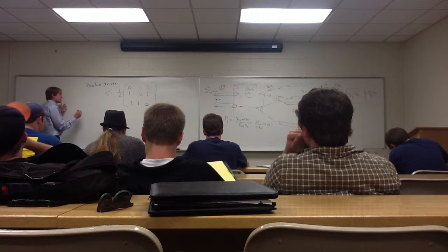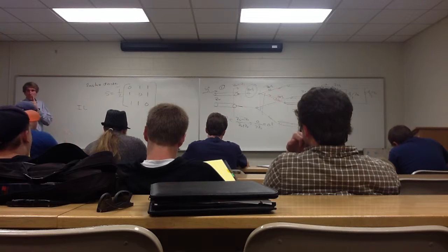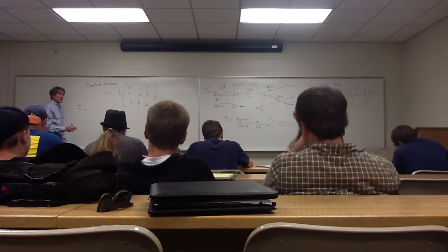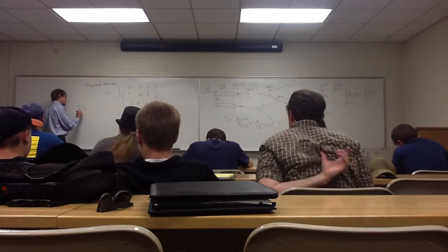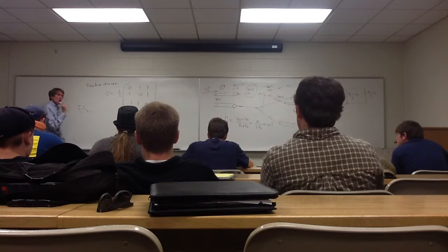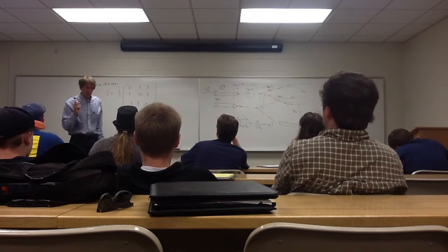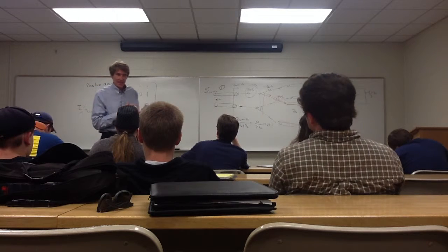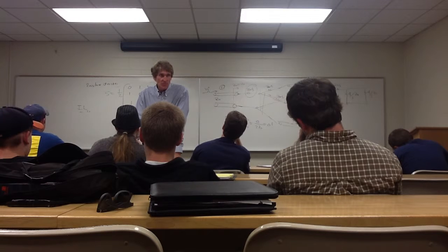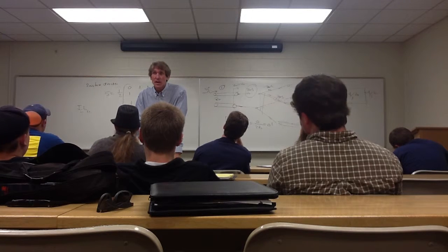Now, if you wanted the insertion loss, take note. This is something people make mistakes on. When we do insertion loss, say for 2-1, write this down. Insertion loss is always going to be looking at the S parameters. Now, what does the reflection coefficient deal with? Power or voltage or current, class?